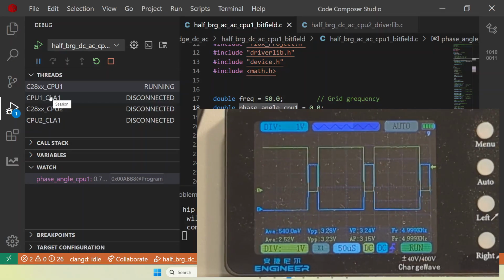And you will see now something very different happens. But now this 45 degrees is the cosine of 45 degrees. And the cosine of 45 degrees is 1 divided by root 2. So which means now this S1 device is going to have a gate pulse with a much wider width, but not near maximum yet, right? So this is something that I would ask you to verify on your own. Take your own time to verify this and figure out if this is what we should get.